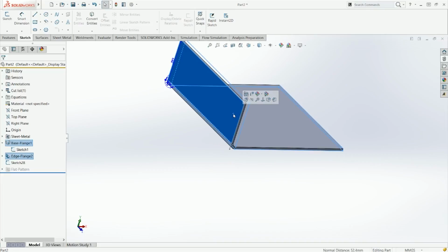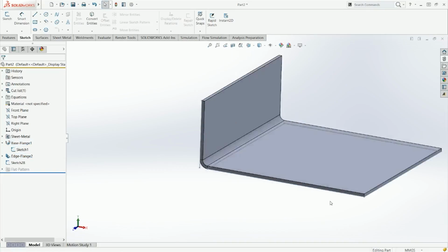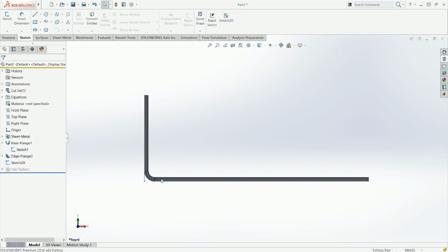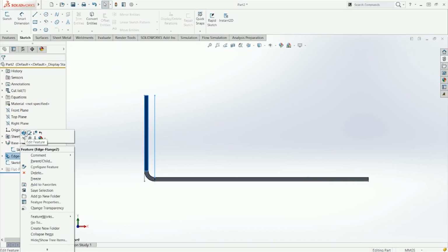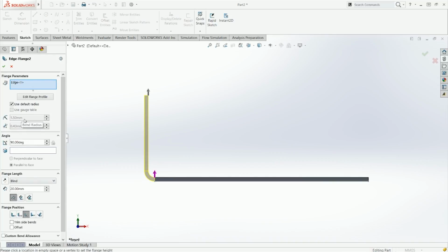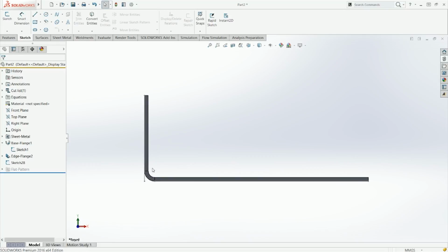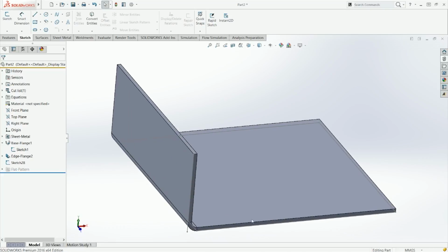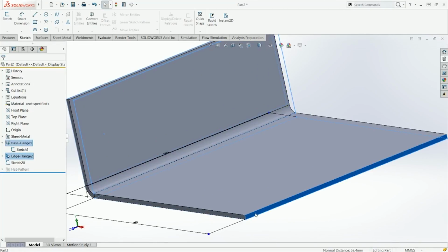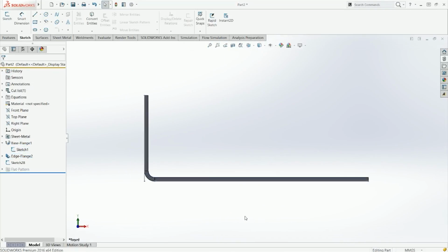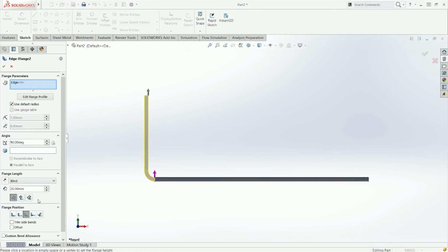Well, it's not going to be a weird number, it's going to be a calculated number. It will be the radius plus the material. In this case the material is 0.9 and the radius was 1.5, I believe. Yes, 1.5. So 1.5 plus 0.9 is 2.4 plus 50, that's going to be your 52.4 right there. So as you see, even though it may look like a strange number, it's actually a calculated one. There is a bend from the virtual sharp.